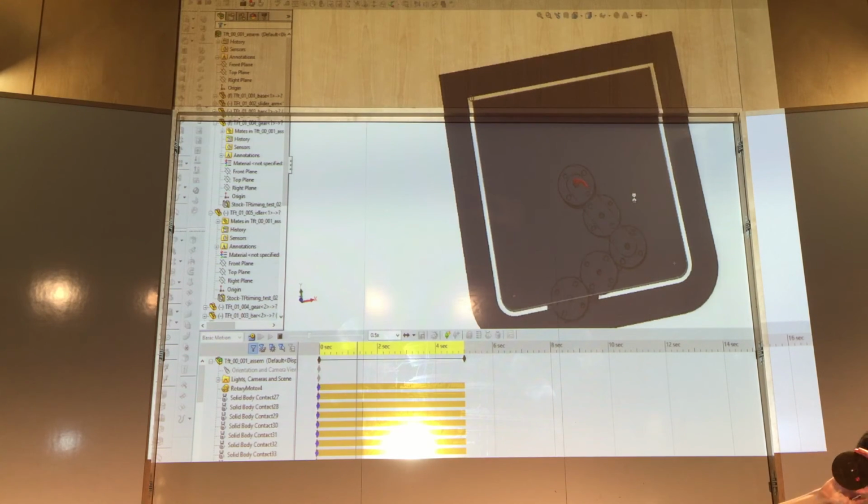So it's essentially a cam follower system, but I want my feet oriented in a certain way, and I want to keep that timing between the output and the input. I was playing with this one, and then I made this one. I knew this thing works, but when I made this, it kept not working a little bit. It was just because I was getting slipping, because I made it out of acrylic and little O-rings.